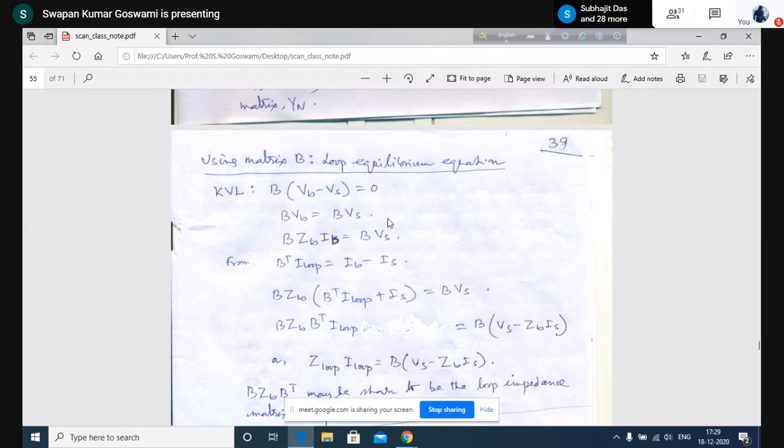An impedance will be negative or positive depending upon the direction of current with respect to the dot. That will be regarding the mutual impedance. So mutual impedance, let us for the time being avoid, because that will create confusion. First of all, try to understand it with the help of self impedances only. Once that is done, then we shall go for the mutual impedance. Otherwise, for writing the self impedance matrix or self-admittance matrix, all elements will be diagonal elements and all impedances or admittances will be positive.